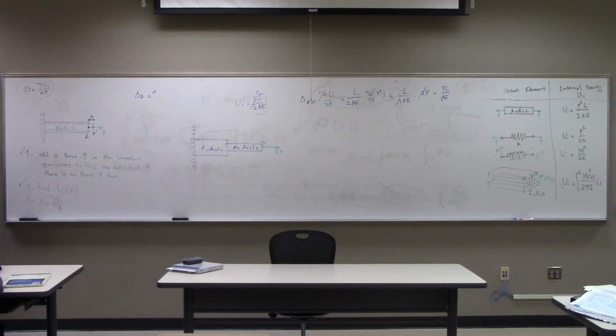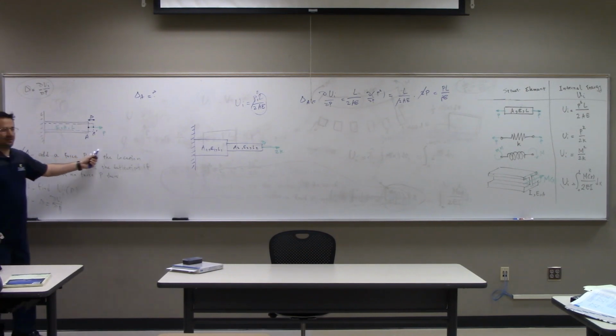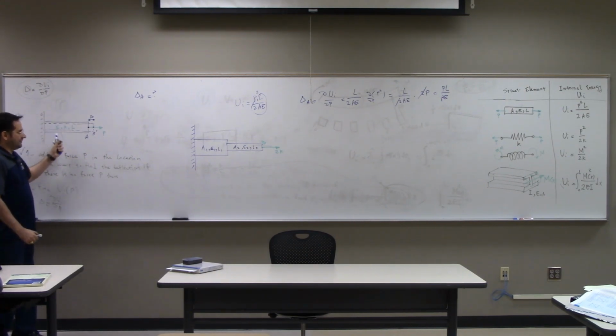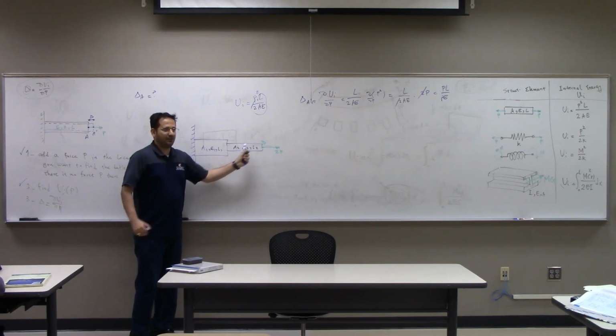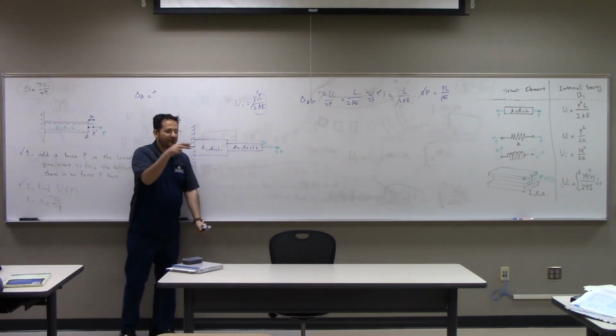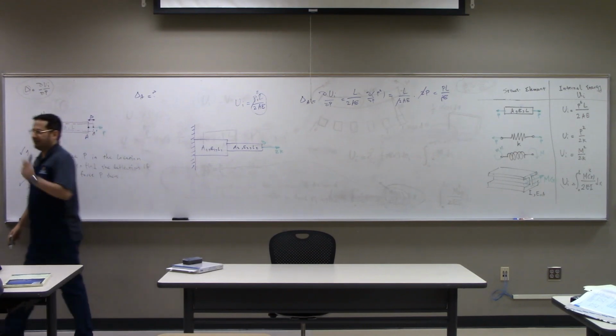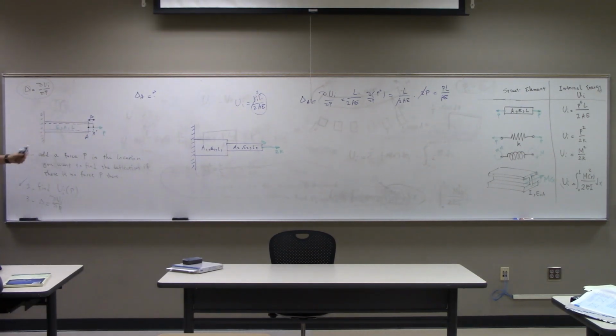Well, if I use the original method, that the stress is equal to E times epsilon, then this is not straightforward, because your stress is different. Here you have a different stress because you have different cross-sectional area. So you have to jump in the axial stress, right? So how can I find the deflection at point B?